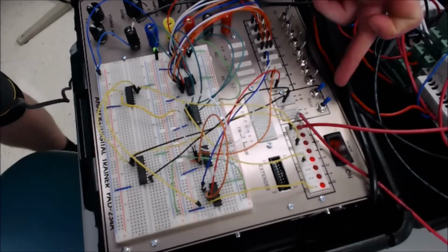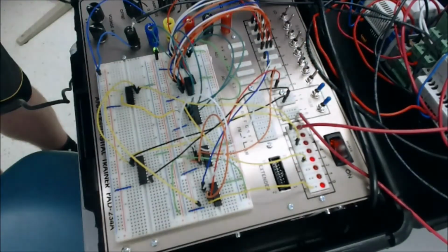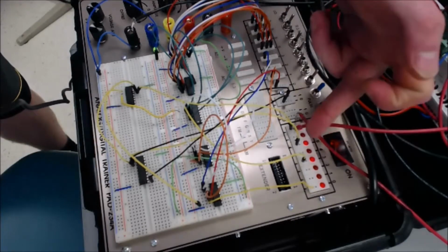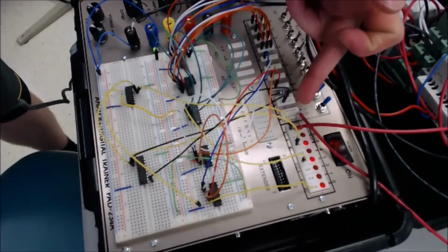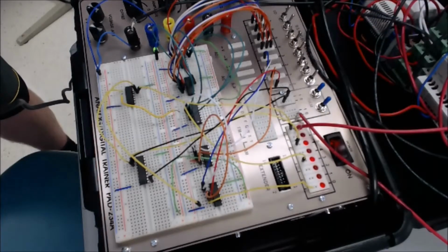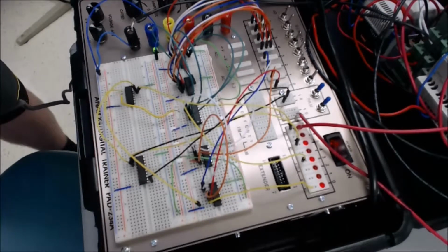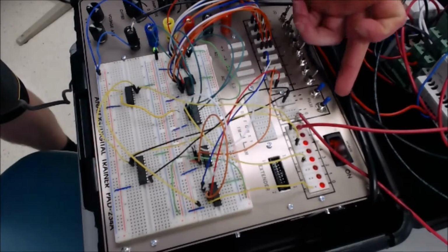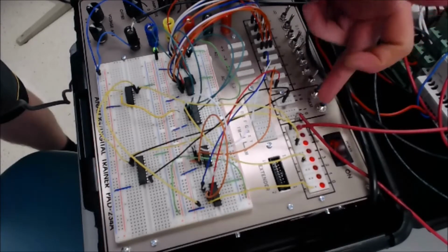Now the third one is the presidential switch, and that is right here, this pulse switch that we can press. And as you can see, as soon as that one turns on, this is going to light up a 4th LED, and this is going to send a signal to the PLC saying that all the conditions have been met, and that's the Skynet countdown. There's going to be a 60-second countdown that starts up on the PLC based on when this input is seen, and then it can only be canceled by pressing the presidential switch again, using this button right here.